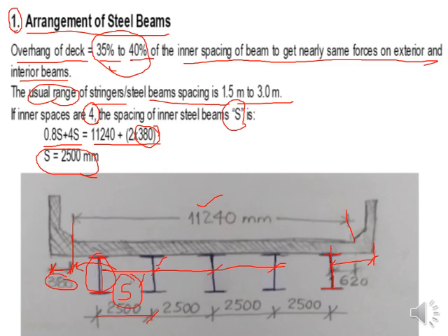So if you see with respect to the roadway width, then from edge to edge, this total distance is known to us. So keep this known distance on one side of the equation and keep the unknown on the other side. The unknown means this overhang part on both sides from the center of the exterior girder, and we don't know the spacing at first.